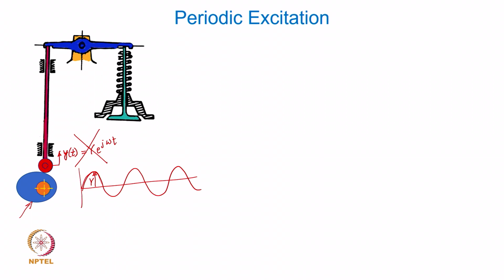In many of the situations we have discussed that yes, we can assume the excitation to be harmonic, and it suffices. For example, all the rotating machinery by default will always have unbalance as a sort of a residual unbalance exciting the dynamic system. So, the harmonic excitation function in terms of the force acting on any rotating equipment is definitely going to be there.